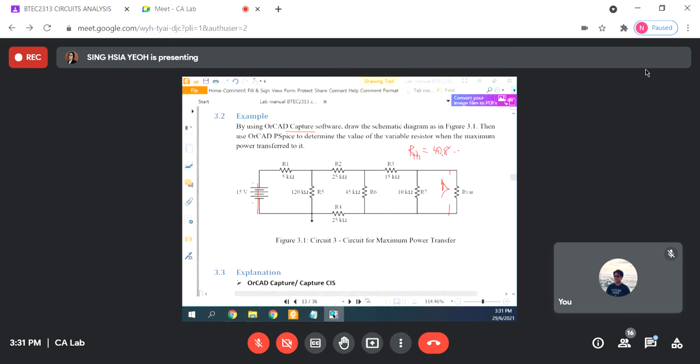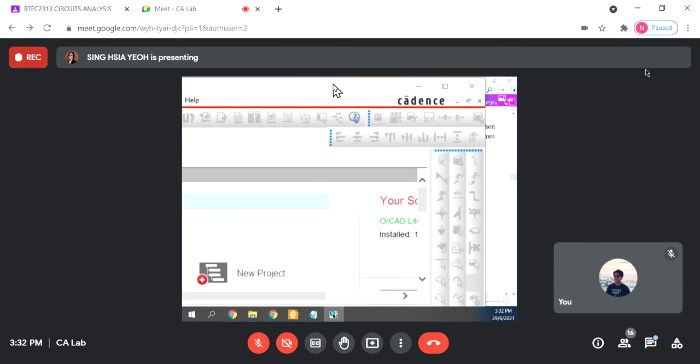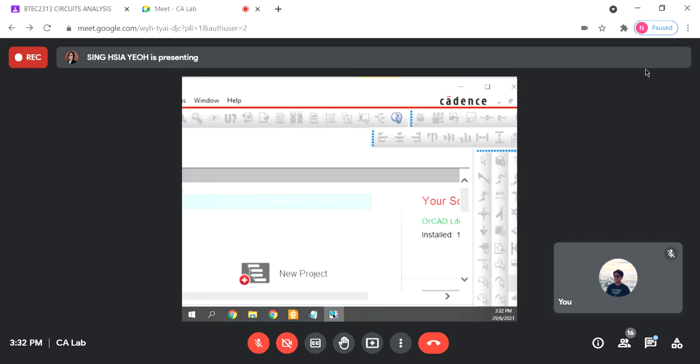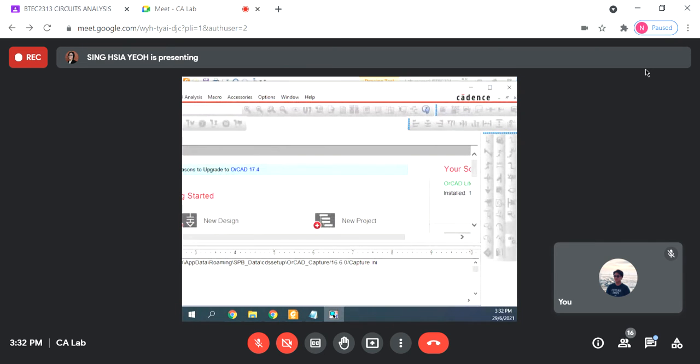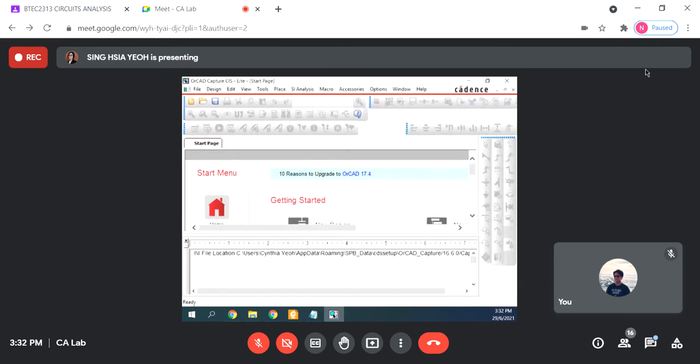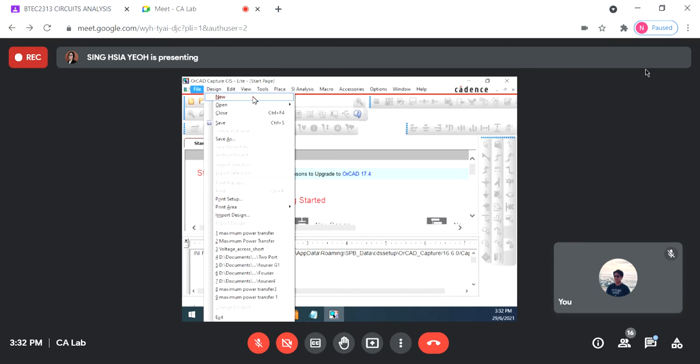You have to close your PSpice AD first. You have to close it first, because if you are not closing it, later when you run the simulation, you will have problems. Okay, you will have something like this, right? Then go to the new project: file, new project.